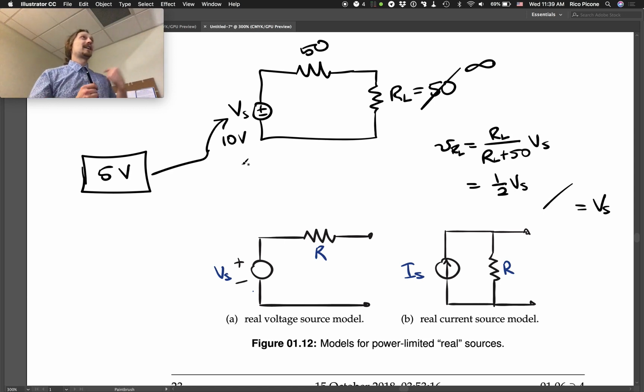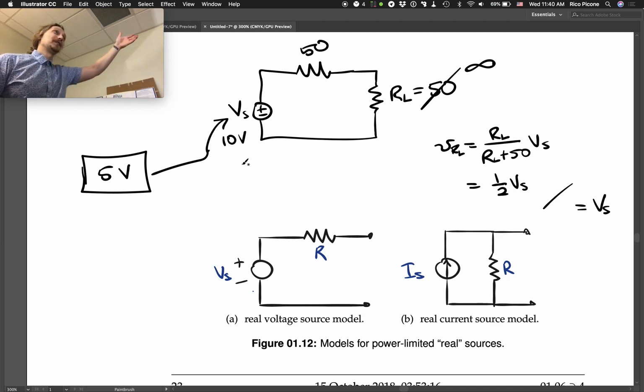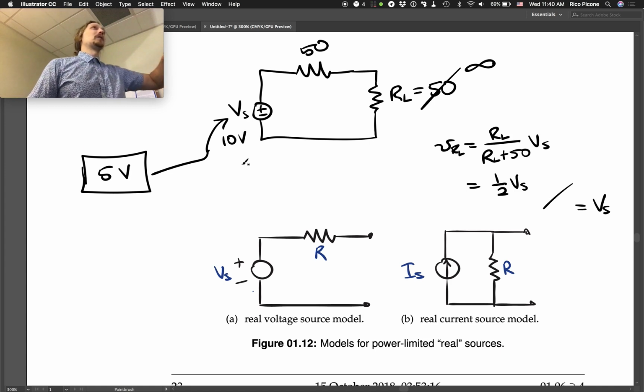There's another setting on the oscilloscopes that I've seen some people get into, and I don't know why, people probably accidentally do this, but you can put in an attenuator, like a 10x attenuator, on a cable going into the oscilloscope. Say you're trying to measure a really large voltage, and you know that your oscilloscope can't go to that high of a voltage, so you put a 10x attenuator on the cable.